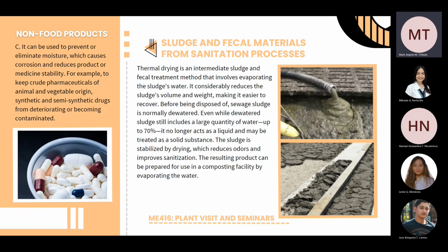So another application for drying is to remove sludge and fecal materials from sanitation processes. So thermal drying is an intermediate sludge and fecal treatment method that involves evaporating the sludge water. It considerably reduces the sludge volume and weight, making it easier to recover. Before being disposed of, sewage sludge is normally dewatered.